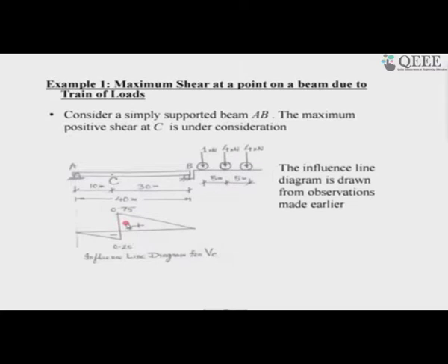When all the loads are just to the right of this section C, I have all the effects of these loads. Now, the distance is constant, suppose the whole system is pushed slightly so that this load crosses the C point, then sitting at this section, if I look to my right, the 1 kilonewton load is gone, it has gone to the left part, and I am left with 2 of the forces. So, that has an enormous jump in the shear force according to our sign convention, sitting at the section.